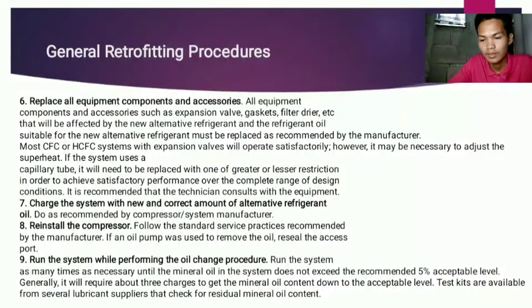Number 6. Replace all equipment, components, and accessories. All equipment, components, and accessories such as expansion valves, gaskets, filter dryers, etc., that will be affected by the new alternative refrigerant, and the refrigerant oil suitable for the new alternative refrigerant must be replaced as recommended by the manufacturer.